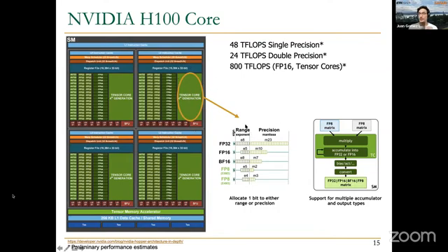In the 4th generation, we also see more heterogeneity in the data types that are supported. These tensor cores support 32-bit floating point operands, 16-bit floating point operands in 2 different formats, and also 2 different formats of 8-bit floating point values. These tensor cores are specialized for machine learning training and inference, neural networks, or deep learning, but they are not the only execution units in one specific device that have been designed for neural networks and for deep learning.